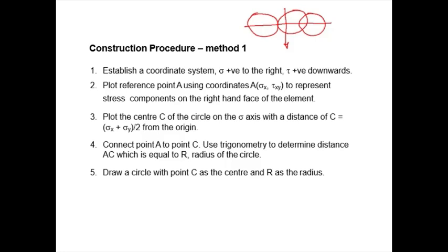Okay. And the other thing is your scale for the axis. This is normal stress, this is shear stress. The scale that you use for this axis, you have to determine carefully so that you don't get a circle which is too small, that will reduce the accuracy of your reading from the graph, or you don't want the scale to be too large, such that when you start drawing the graph, you find that the graph exceeds your graph paper. Okay, you don't want that to happen. That is the only setback of using Mohr circle on graph paper, right?